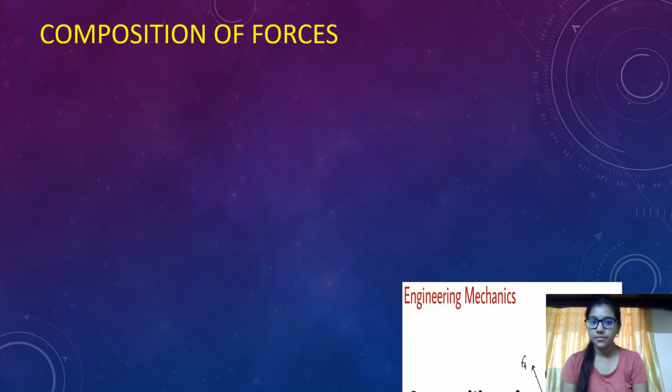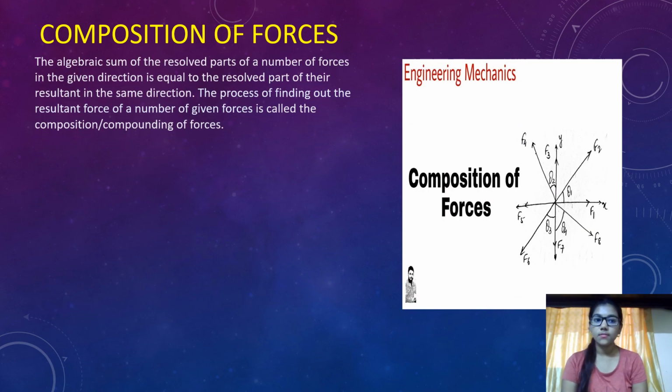Composition of forces. The algebraic sum of the resolved parts of a number of forces in the given direction is equal to the resolved part of the resultant in the same direction. The process of finding out the resultant force of a number of given forces is called the composition or compounding of forces.